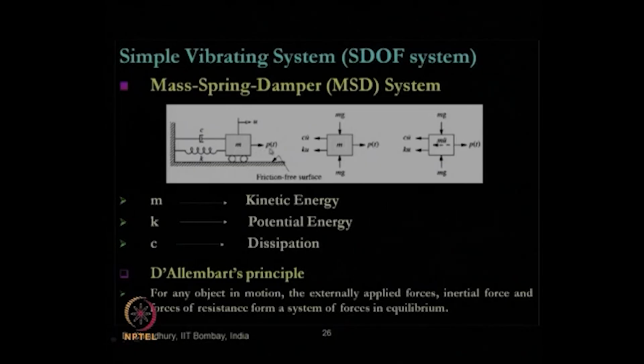So this is the dynamic load, the load which varies with respect to time and creates a vibration in the system. This is a friction-free surface with rollers, so the weight, the static load, will automatically be balanced through the roller reactions or support. So we are only discussing here the dynamic component of the forces present.